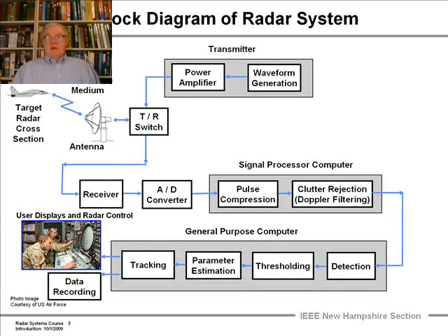And these days we have very sophisticated digital displays, and also to record the data if that's an important function of the radar, so that analysts later can look very carefully offline at the data to understand how well the target was tracked, how well the radar worked, and to tune the radar in whatever means is necessary, so that it's operating optimally.